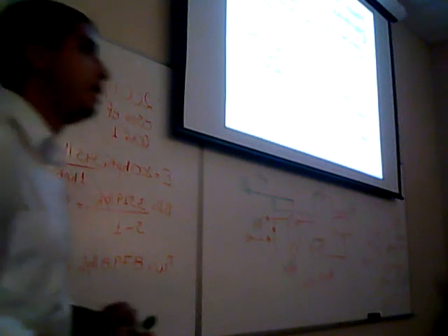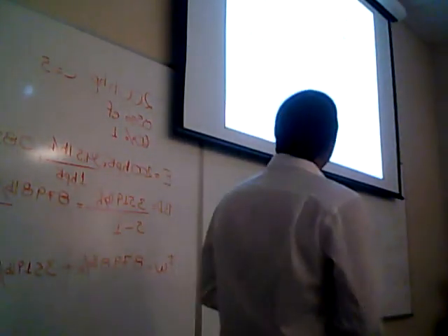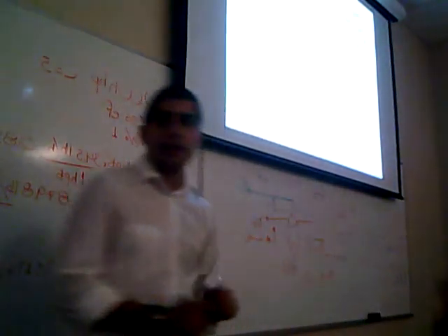It's important to have a maintenance plan for the steam trap. Surveys have shown that major industry plants with a regular steam trap maintenance program show an average of 10% of all the steam traps to be inefficient.